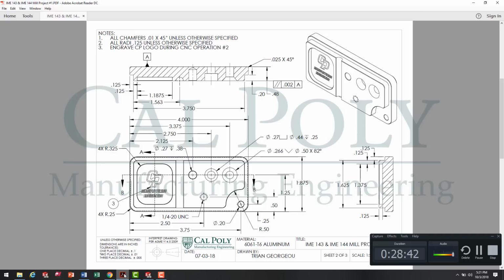So now when I go back to the engineering drawing and compare, you'll see it looks very much so like the example in the lab manual. Now don't fret if your hole diameters are slightly off from what this drawing says in the tutorial video. The true drill size is a 0.257, and we'll have a Rev C of this engineering drawing coming out any day. The whole idea was to understand how to model, use the hole wizard, create the hole callouts in the engineering drawing for this project, not to fret over a few thou difference in your hole size.